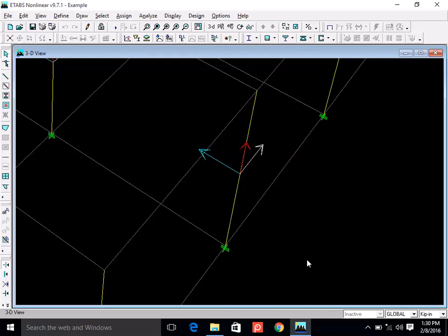In case of beams, generally the loading is gravity, and earthquakes affect columns much more than beams. So in case of beams, our shear force mostly is about axis number 2. If you see shear 3, horizontal shear, that will either be absent or it may be absolute minimum.